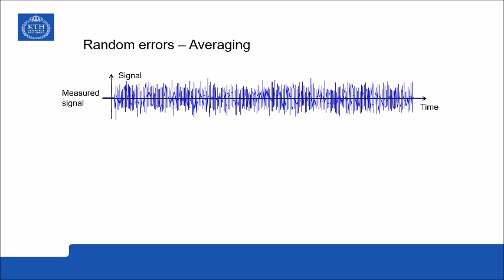Well, here we have the measured signal again. So what is done is simply that we divide the signal into segments, segment 1, 2, and so on. In this case, it's up to 8 segments. And the signal segment length, Tm, is defined as the new measurement time.